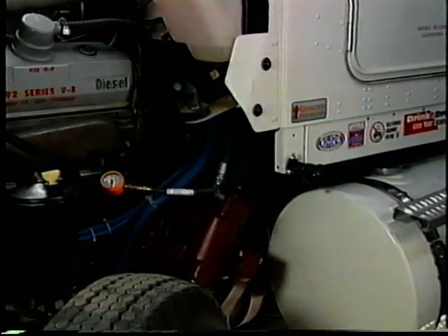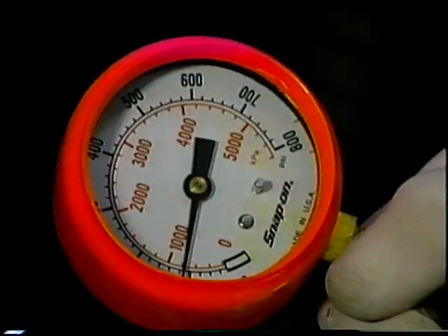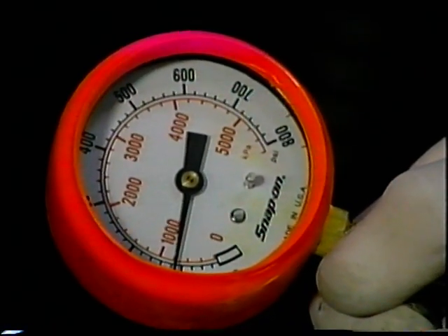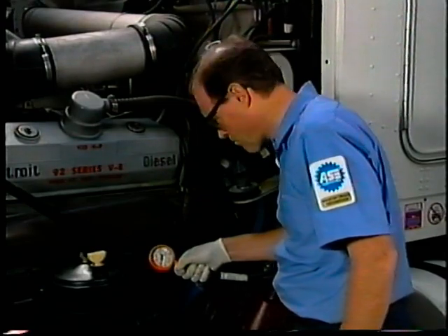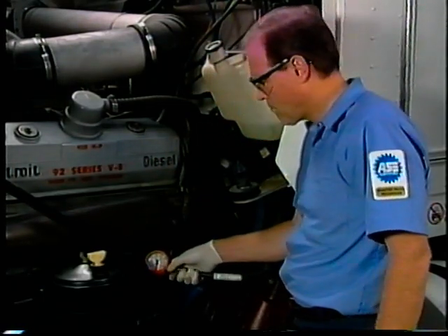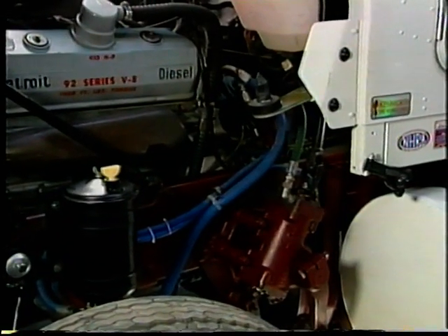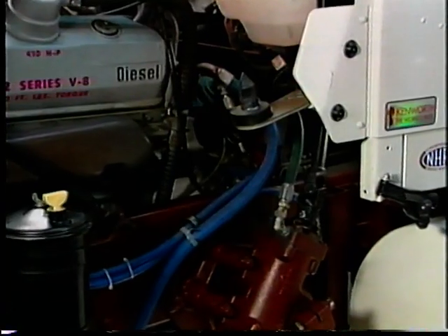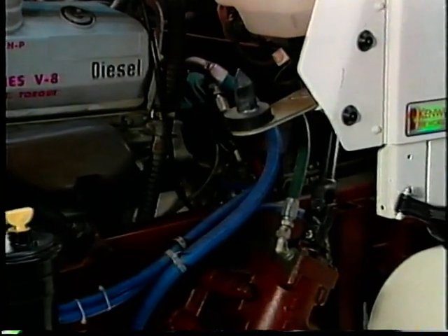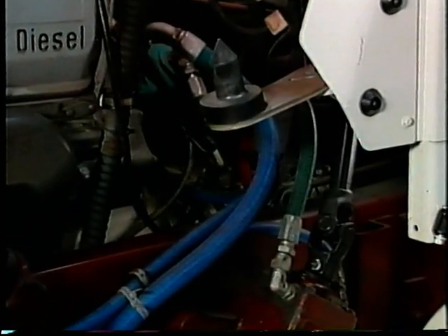Always exercise extreme caution when working around power steering systems because the fluid pressure can exceed 2,500 psi and the fluid temperature can reach 180 degrees. The test procedures will show problems with restrictions in the high pressure or return lines and pinpoint a worn pump or stuck control valve or troubleshoot internal steering gear leakage requiring repair.